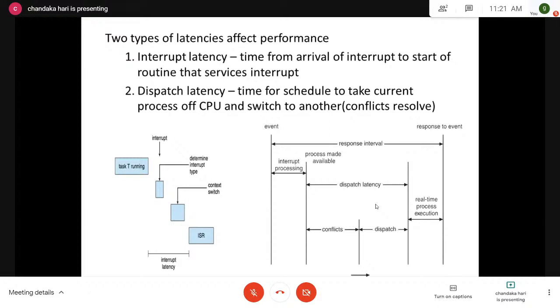So the minimum time required for switching from one task to another is for doing these three activities. Let us take that in order to do these three activities, I will take 10 milliseconds. But if any high priority interrupt is requesting a service within 5 seconds, I cannot provide it. So I cannot design a real-time operating system. In case you want to design any real-time operating system, whatever time limit is required should be within acceptable limits.